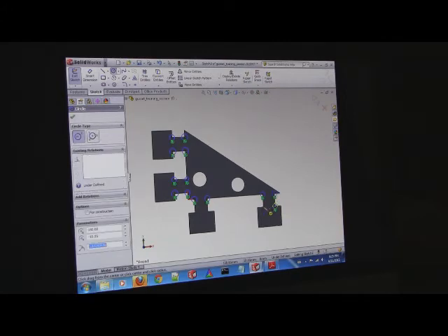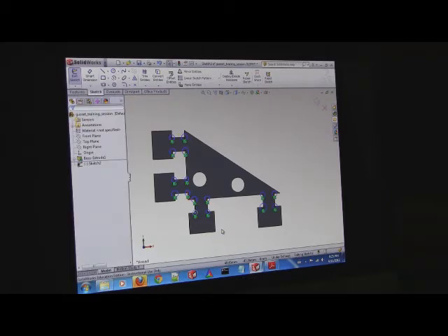Does anyone know why I'm even putting these circles for the physical part? When you fit these parts together, mathematically for them to fit, they have to be perfectly 90 degrees with no radius. The laser cutter has a radius of 0.005 of an inch, which is just enough to make sure that your gears don't assemble properly. By putting these little circles, we're getting rid of that radius. It's called an undercut. So then we're guaranteed no material will ever overlap.